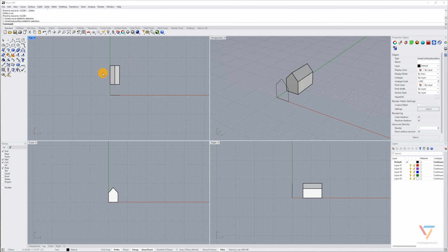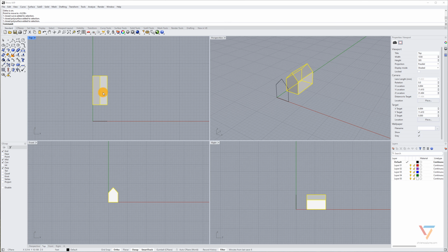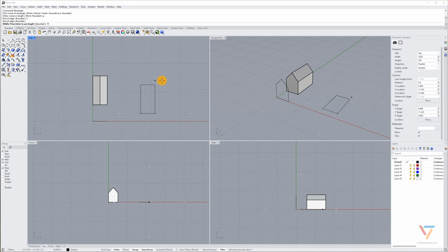We can use the objects that we see here in these views to create flat drawings. So let's say, for instance, I was going to make a drawing of this top view. So not a 3D model, but I could do that. I could use a rectangle, and I'd want it to be aligned, but for right now I can just put it wherever I'd like. And I know that it's going to be a 3-point rectangle. It's going to be 5 feet wide and 10 feet deep.